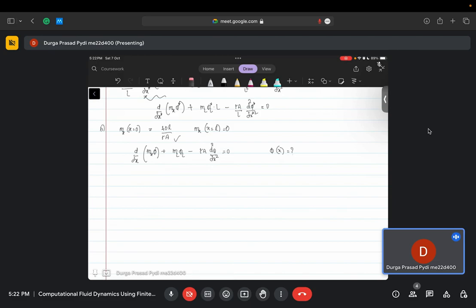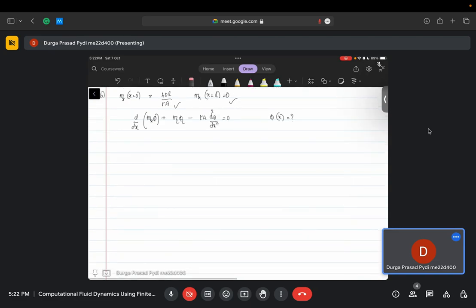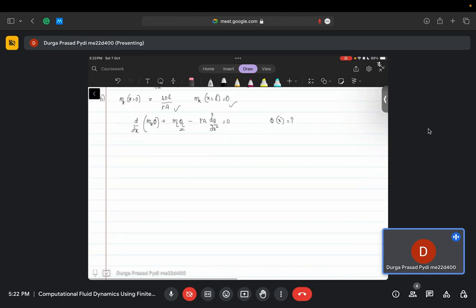These boundary conditions for mx are given. In this equation, the first unknown is my phi l. To know the value of phi l, we need to know the value of ml. So phi l is phi if ml is positive, or it is phi 0 if ml is negative. But the question gives you only mx, so how do I go about finding ml?